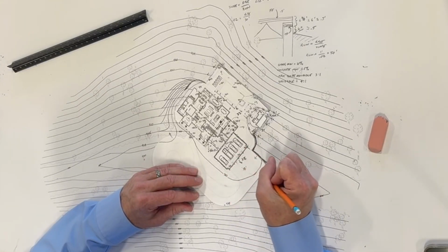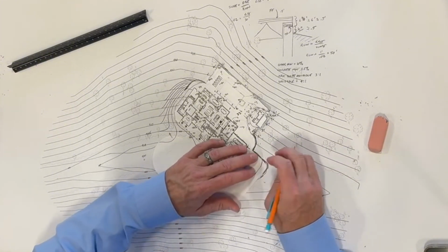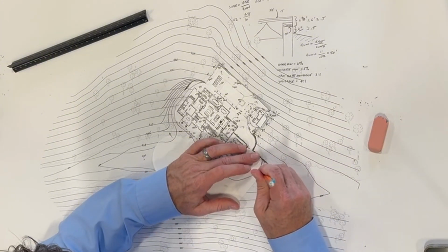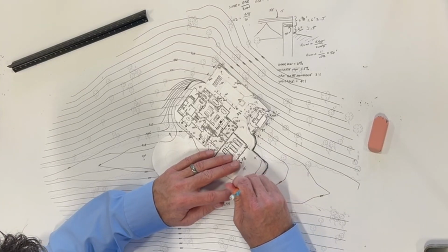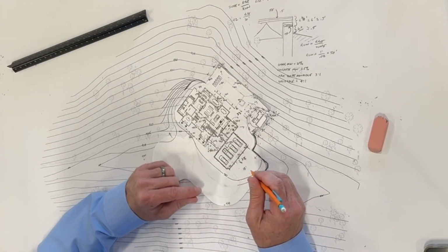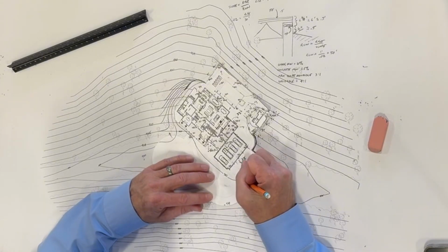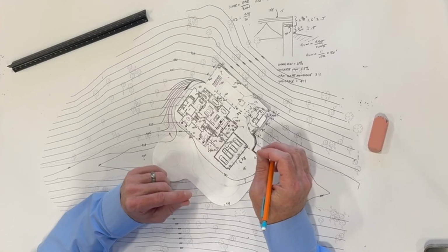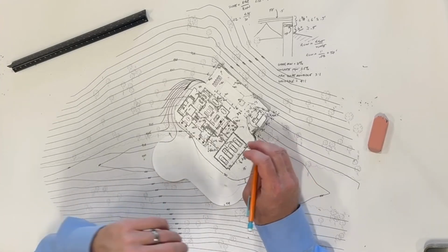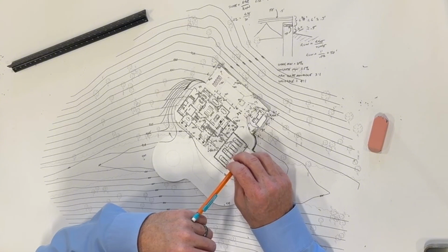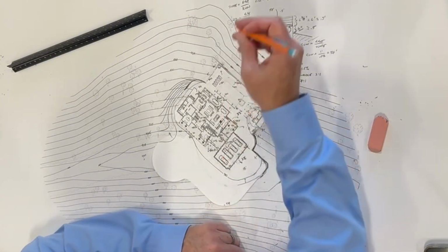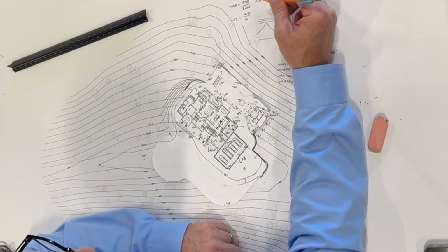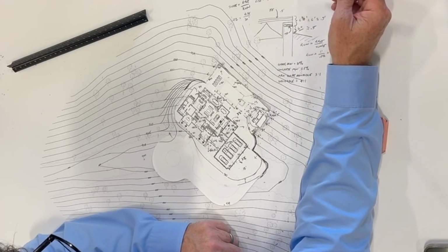Maybe I'm going to bring the 939. Here's the retaining wall, kind of right to that edge of the retaining wall. So 939 kind of right there. Again, you don't want this to get too steep right here, right? Because this is your driveway now. And so the steepest driveway you really want is probably an 8% driveway, right? Anything more than that is going to be just too steep. So if it's 8%, the question is how much run is there in between?